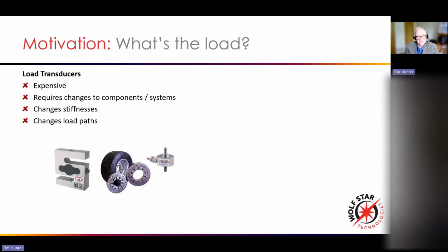And then to add insult to injury, when you bring those loads into the structural analysis team, the analyst is typically working on the as designed part, and they've got to rework their FEA model to look like the test part in order to use the loads you just measured. Okay, so it's not great, but this is a traditional approach that people use.